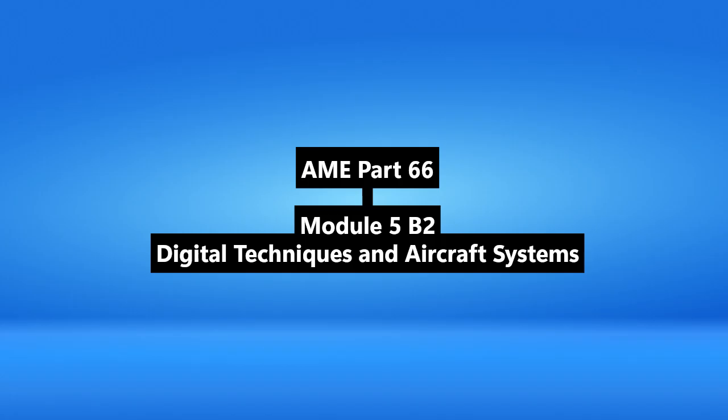Yeah, so how sensitive are these parts? The module mentions classes. Right. Standards classify devices by the ESD voltage level they can withstand. Class 0 is the most sensitive, damaged by less than 250 volts. Class 3 might handle up to 8,000 volts. A lot of modern avionics components are down in those more sensitive classes, and they're getting more sensitive as things get smaller. That's why the precautions are so strict.